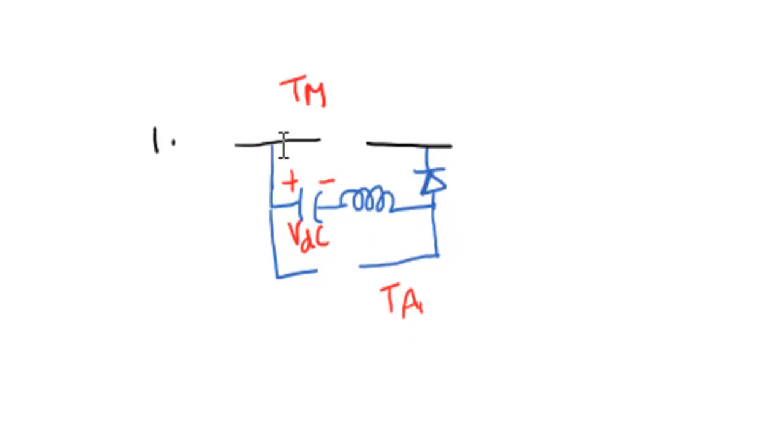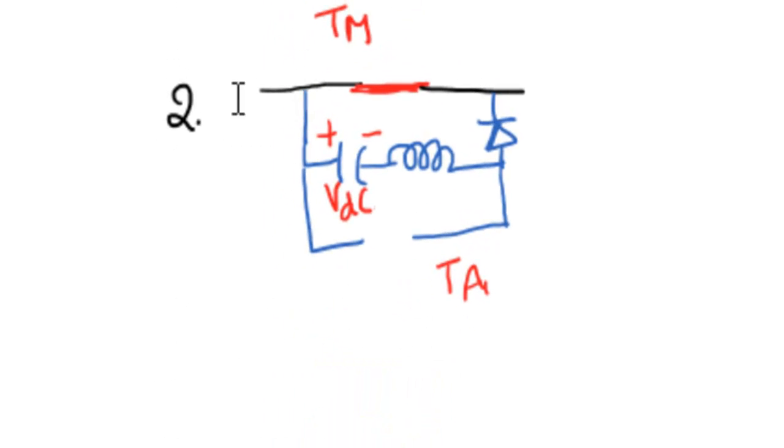And if you look at that, when the main thyristor is turned on, obviously this thyristor carries the load current I0, which is supplied by the source. Even if this capacitor tries to discharge in this way, this diode will not allow it. That's why the capacitor voltage remains the same at VDC, and the current flowing through the tank circuit will be 0. That means through the main thyristor only the load current will be there, no other current.